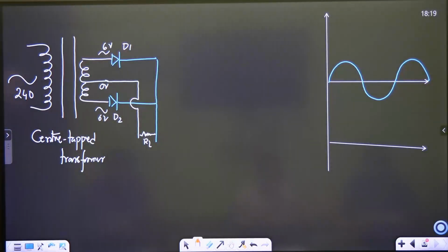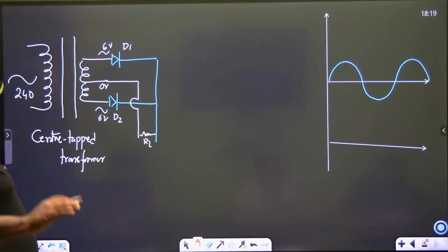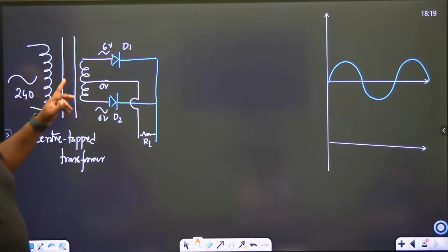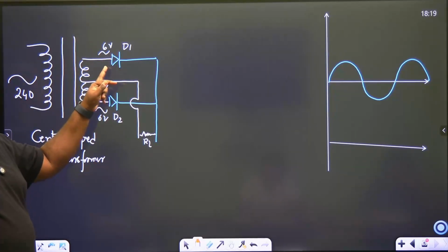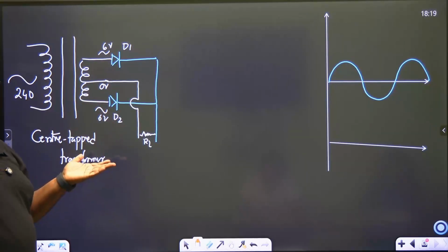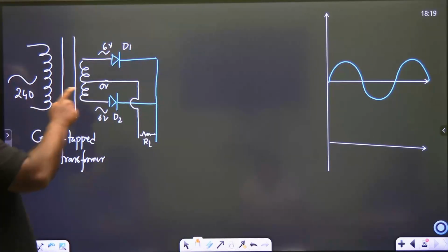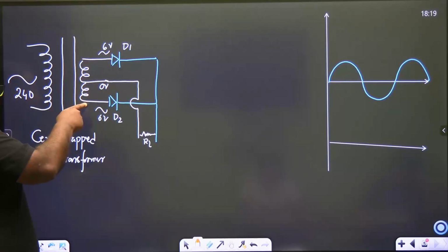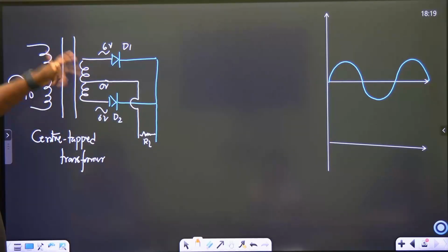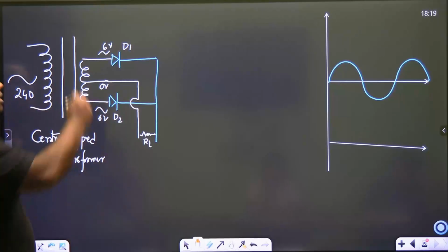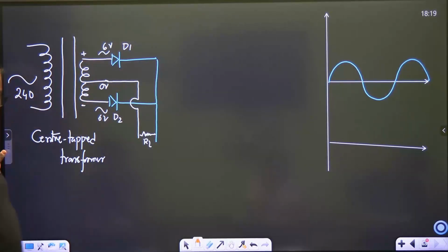Okay? Now you have to be very careful. Diode D1, D2. Right. Now take one signal, take one pulse. When diode D1 is sensing a positive bias, don't you think diode D2 at that time will be sensing a reverse bias? Yes, at the same time. See, this is a pulsating signal. This is 0. If this fellow becomes positive, this fellow becomes negative at that time. That positive negative is pulsating. How much? 50 hertz. In 1 second, 50 times. It's changing. So at some instance of time t, say this is positive, then this fellow should be negative.